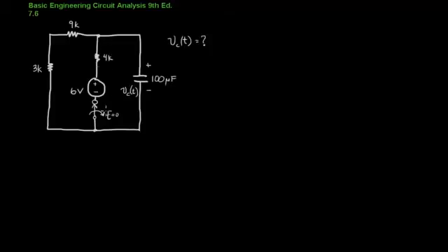So how are we going to solve this? Well, we have to remember two basic things about these new components that we're working with. In a circuit like this, that's been allowed to sit for an infinitely long time, we treat a capacitor as if it's an open circuit. I tend to remember this because if you look at the capacitor symbol, it's not actually touching, so it kind of looks like it's open. And the inductor will work the opposite way. You'll treat it as a short.